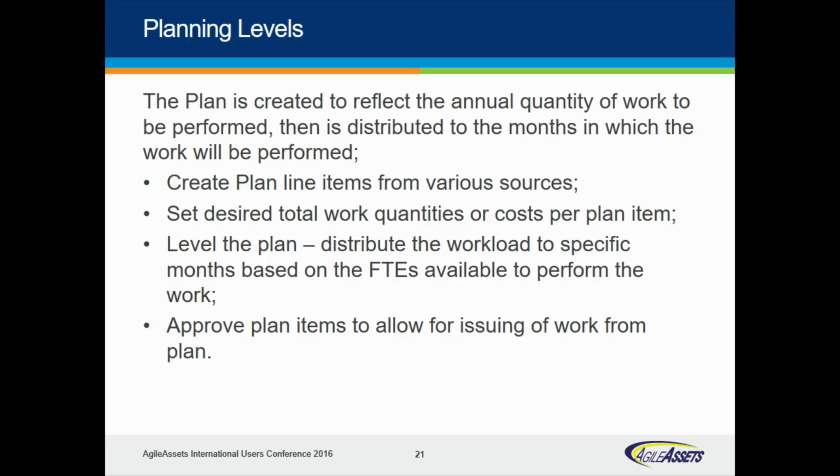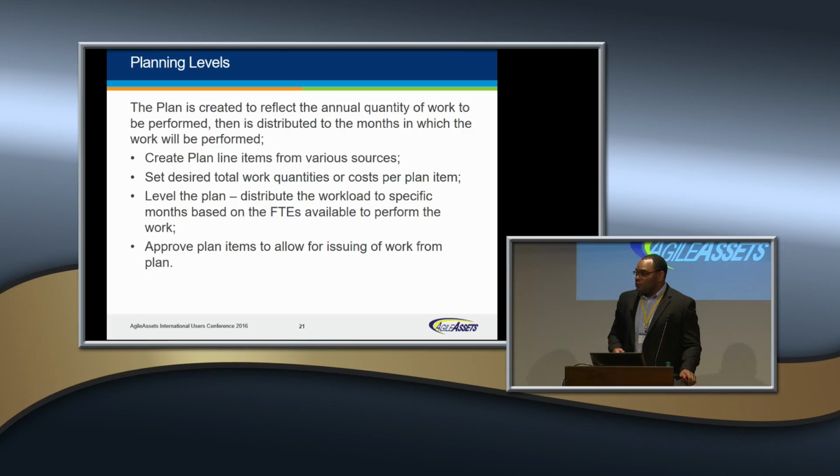We then level the plan, which is we make a determination of when we're going to do actual activities. Now, for certain activities like snow plowing, you know these are going to be done in certain months. And then we have things like patching or overlays, which again, we can only do in certain months where there's no snow on the ground. So these, we basically have set periods in which we can actually perform them. So leveling them is fairly easy. But then there are other more flexible activities which we can essentially fit in when we actually have the FTEs to actually perform that work.